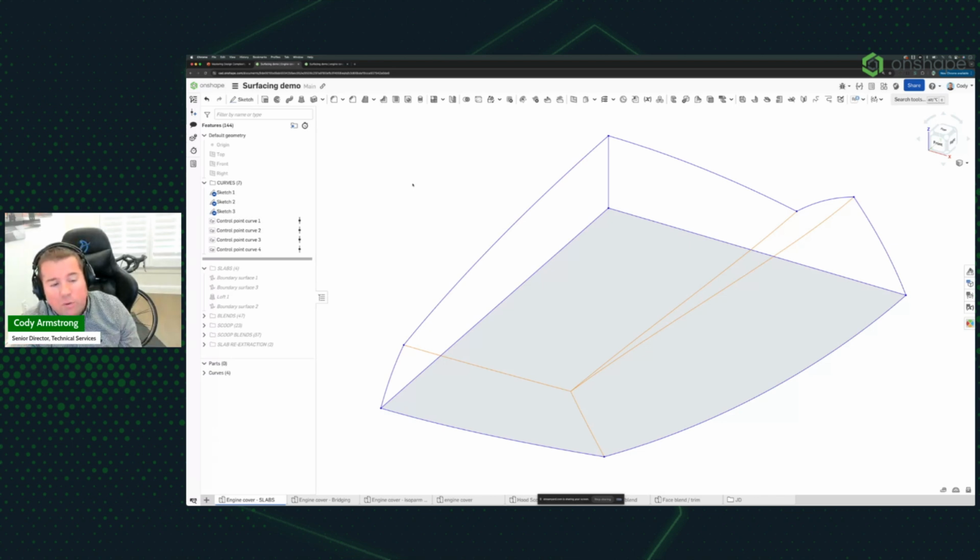So one big tip that I have for you is, add those colors, and whatever color scheme you define is most useful to you. Define the colors of the geometry as a way of delineating them, so that at a glance, like we're looking at it here, I can tell the difference between the 2D sketch geometry and the 3D curves. And while this is only a handful of pieces of geometry, if this had dozens or even hundreds, you would really struggle to discern from the wireframe fog what is what. And so that's where I think colors are really applicable.